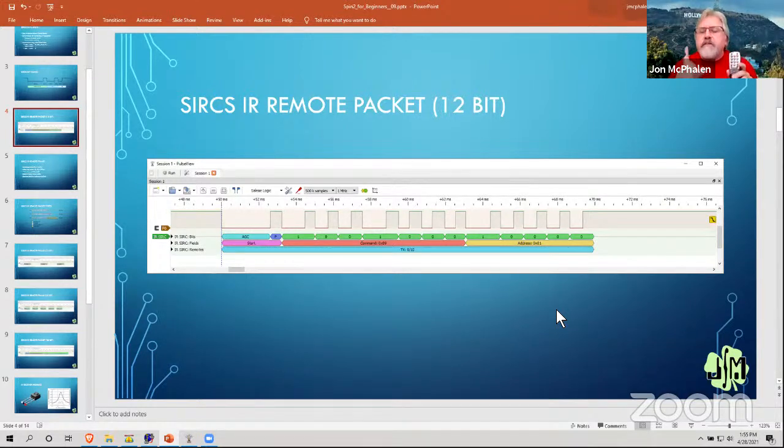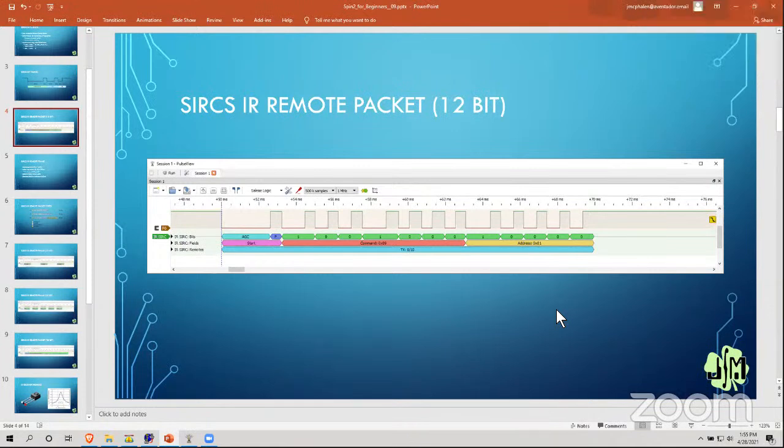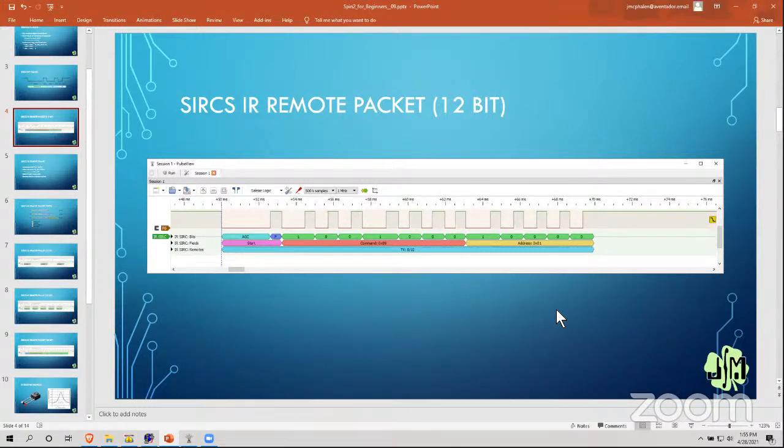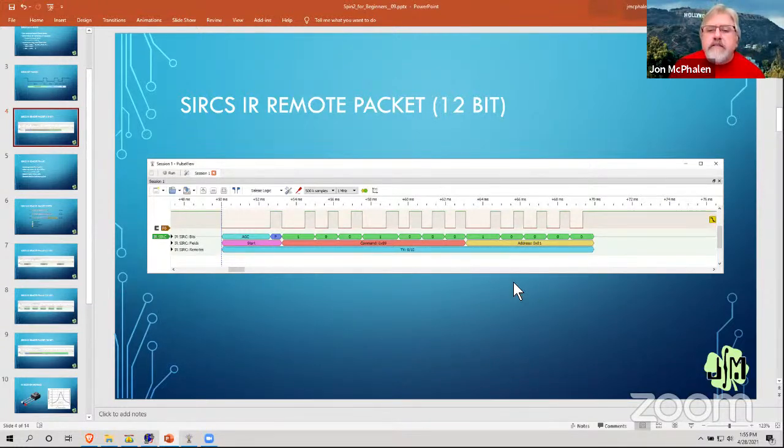These second 5 bits of 1, that's the TV. All right. This DVD remote has a different device address. Of course. So what you decoded was basically all zeros in the first one, and then a 1, or was it the other way around? Yeah, it was. No, it was, Mike, because you can see the 1 is right here. So these are LSB first, these values. Okay.